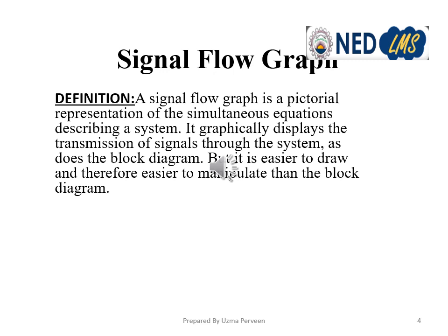So this is the same thing I have discussed, that signal flow graph is actually the representation of the system. We construct the signal flow graph using simultaneous algebraic equations of the system. Signal flow graph actually gives the cause and effect relationship of the linear systems that are modeled by algebraic equations of the system. Each and every equation of the system is in the cause and effect form, and this cause and effect form is depicted by the signal flow graph.